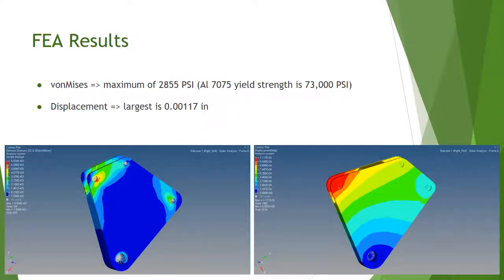FEA simulation is run to ensure the defined case above is satisfactory. Since the FEA is able to run and has output reasonable results, it is safe to say the rocker setup is ready for topology optimization. From here, optimization objectives, responses, as well as constraints will be created to decrease the amount of volume and ensure that the displacement of the rocker is not significant.